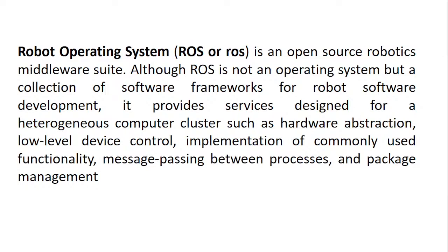The data from a stereo camera or 3D camera will be totally different from the data from a 2D LiDAR sensor. A LiDAR sensor will give a 2D map with point cloud lines, and a 3D camera will give a 3D image, a space structure of the environment.